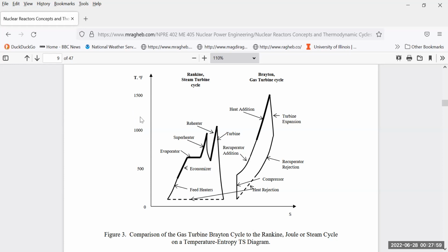Operational temperatures in Fahrenheit are not very high. They are in the range of 500 to 1000, the best that you can get with the steam turbine cycle. So the attention of the designers for new designs of nuclear reactors is to improve the efficiency. Hence, we need to operate at higher temperature. So under consideration is the Brayton cycle, also called the gas turbine cycle.